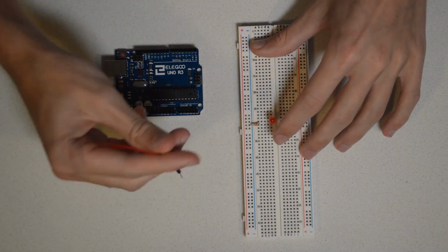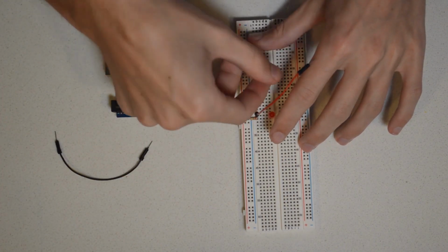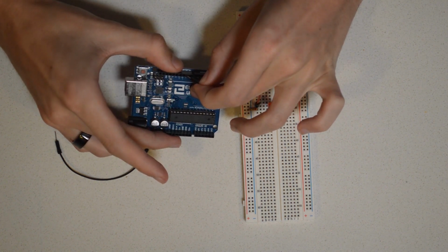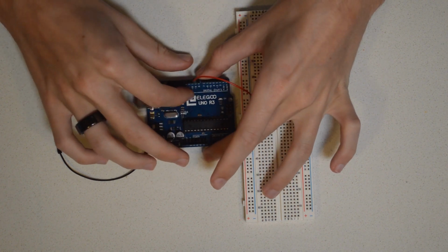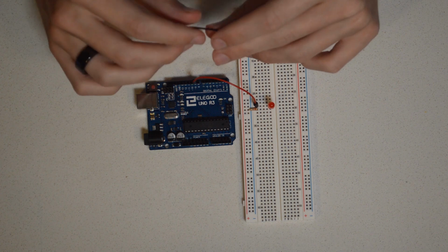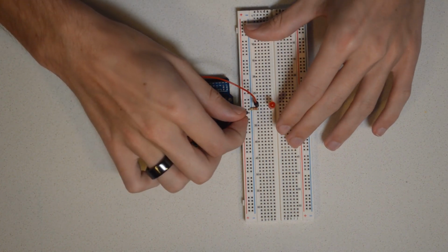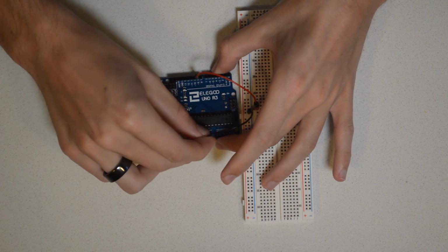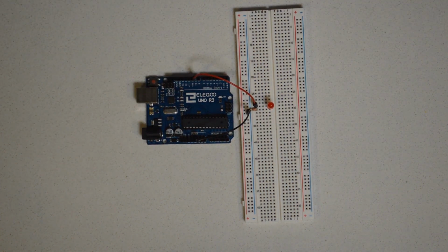Okay, now let's take this and then wire that into PWM9. So the only difference here with the squiggly line, as you can see on the board, that means you can control the amount of voltage that is being put to that output. So then this one goes to ground. All right, let's wire it up. Let's go ahead and hop in the computer and code it.